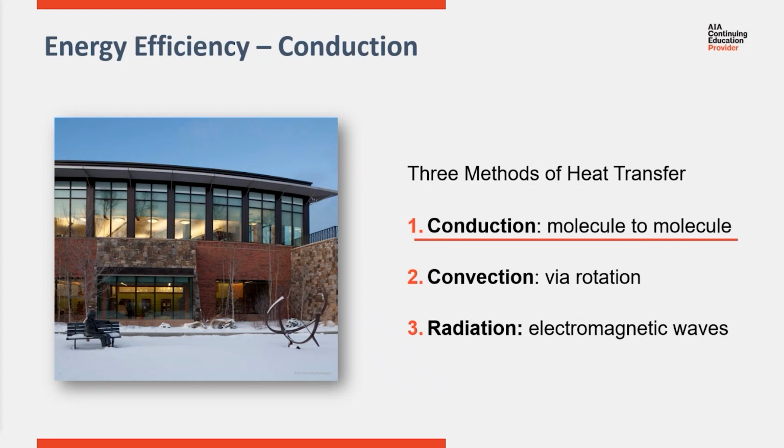Because aluminum is very conductive, framing systems without deliberate attention to heat transfer are susceptible to substantial heat transfer due to conduction. Again, this is a concern for the design team. They need to have a strategy to restrict heat transfer through conduction.